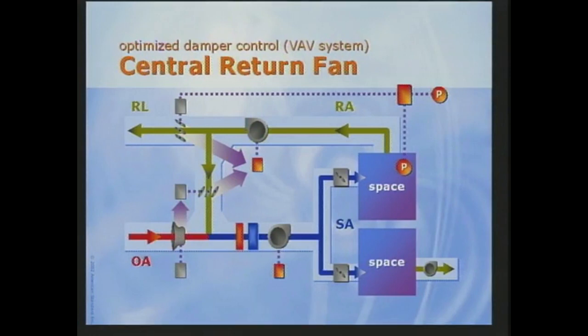Instead, we sense relief air and return air damper position. The return fan speed is then modulated to keep one of these two dampers nearly wide open. This minimizes the pressure needed for both relief and recirculated airflow, which reduces return fan horsepower somewhat and can eliminate this sensor altogether. With proper field engineering and balancing, this approach can help to solve one return fan control problem.